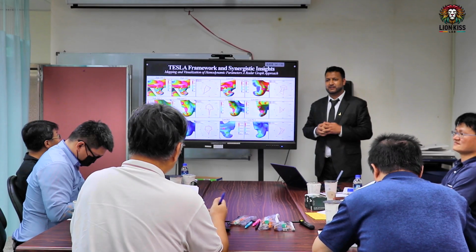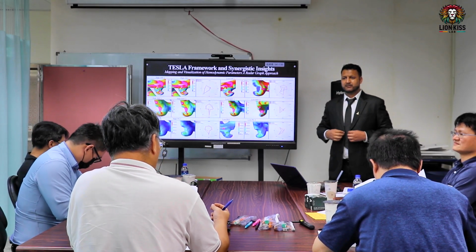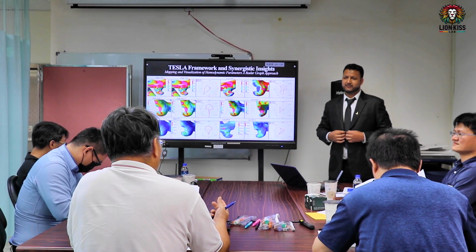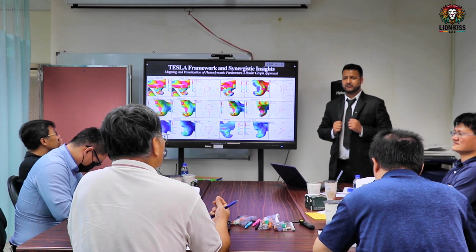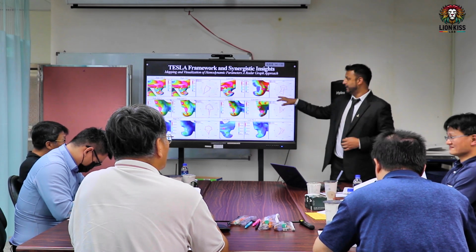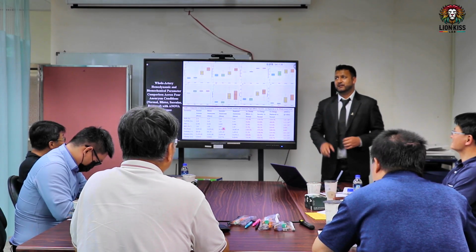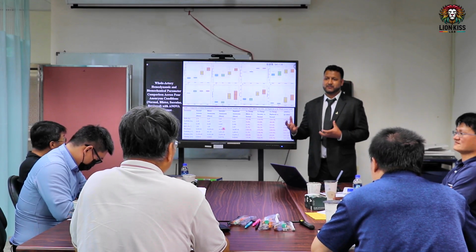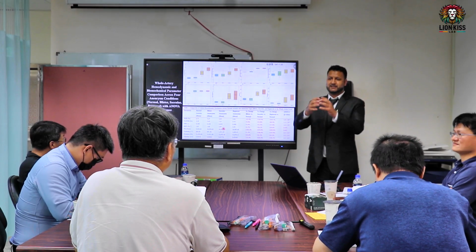Okay, so usually you will suggest the largest wall shear stress is the place to rupture. Rupture in aneurysm, yeah. And the largest wall shear stress usually happens at the neck or dome. Yeah, if we compare, the neck is high, but maybe it helps to increase the size of the aneurysm, but it's not causing the rupture, because mostly rupture occurs in the dome because it's expanding.